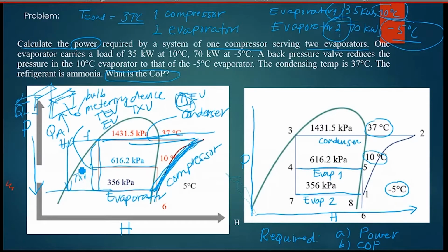So when it registers some kind of temperature from the room, it will correspondingly change the opening of the valve, the ball valve. There's a spring there, there's a bulb, there's a valve head and everything, there's a balancer and everything.